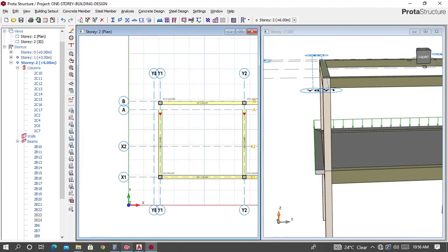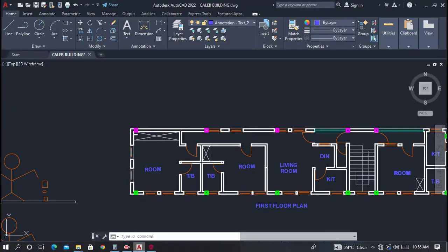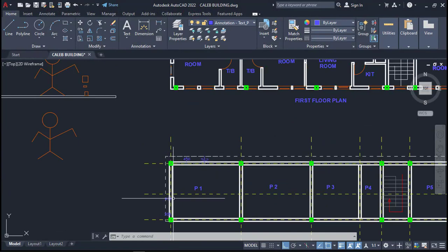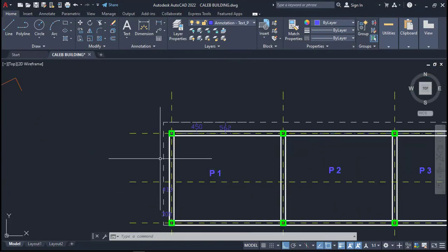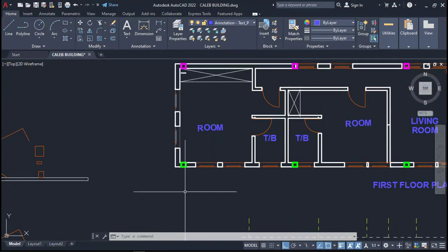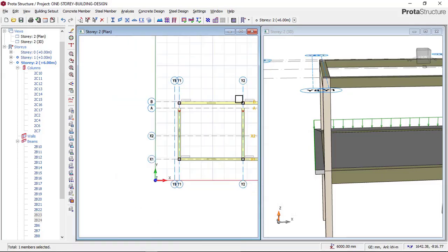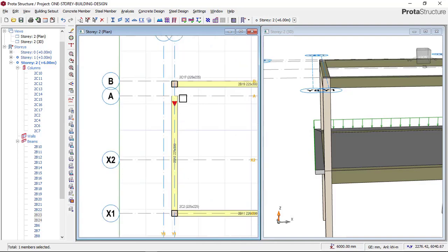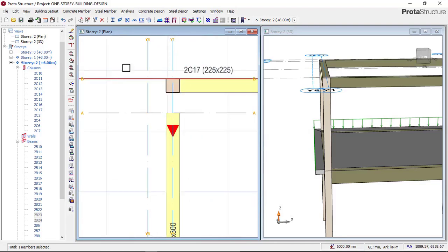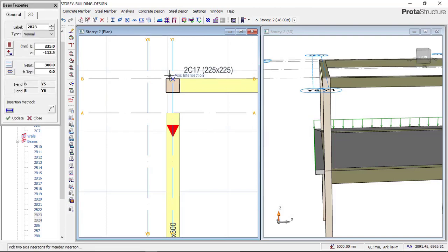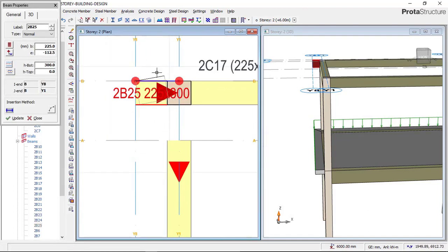You can see it there, because on our plan view, this beam that is on the ground floor shifted onto this very end. As you can see here, this beam shifted to this very end to flush with the cantilever. So we will also shift this beam to flush with the cantilever. This place will also have a cantilever beam. So I'll go here, cantilever, and then provide the cantilever beam from this point to this point. We are okay, you can see it.